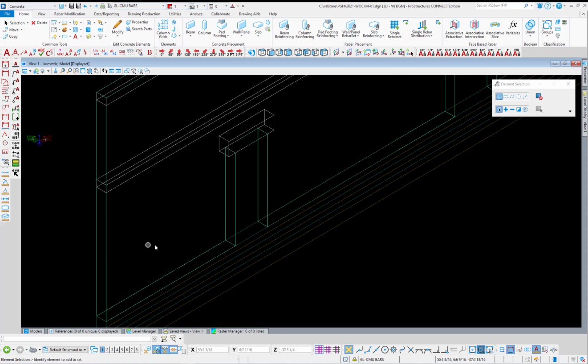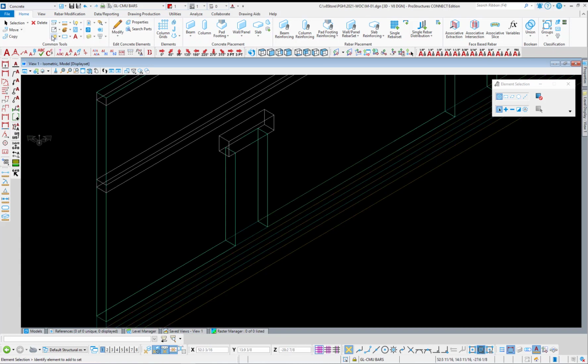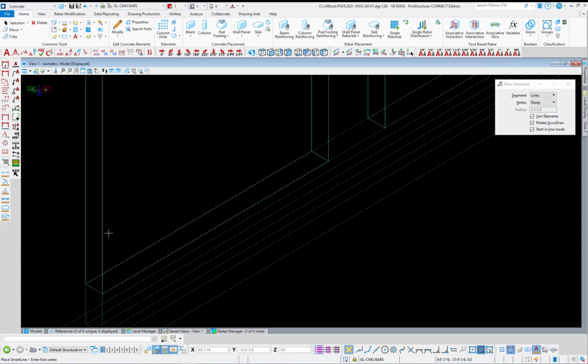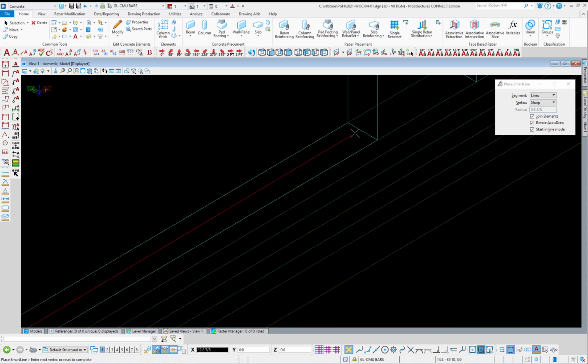Now, how does it work? First, we're going to wind up drawing a guideline for my masonry, which includes a couple vertices. So in this situation, we're going to start here in the corner. I'm going to say O for origin. I'm going to come in 4 inches. I'm going to come in 8 inches. I'm going to draw a line over to my other side. I'm going to say again O for origin. I'm going to come back 12 inch, come back forward 8 inch.